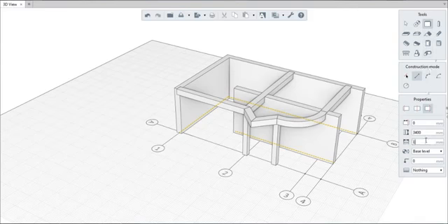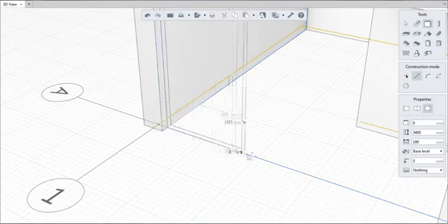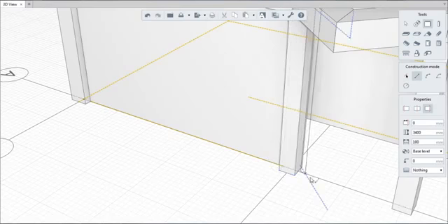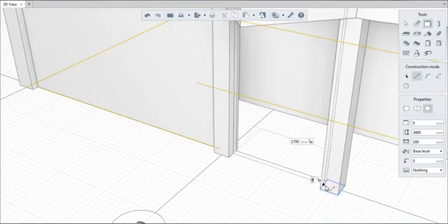Now build a wall sized 100 mm thick by 3400 mm high using object snapping. The wall for the gate and the internal partitions are built with a baseline to the right of the object setting by picking points from the left to the right.